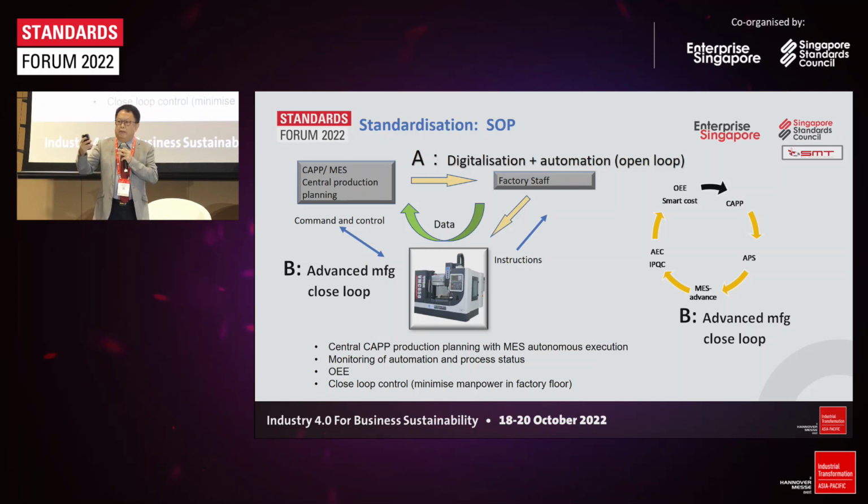It means that when a part is halfway made, let's say it's a WIP, work in progress, you can bring this part to the quality control equipment for testing or measuring. If you find an error, the quality control system will be able to communicate to the production machine to do auto error correction by itself. So you don't have to have humans there to do these actions.